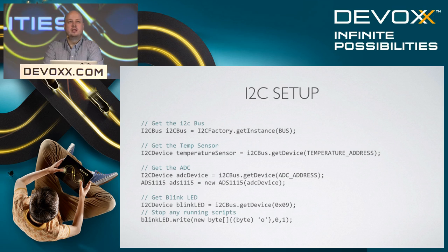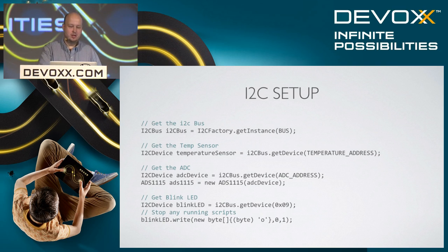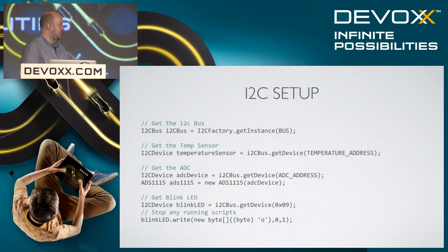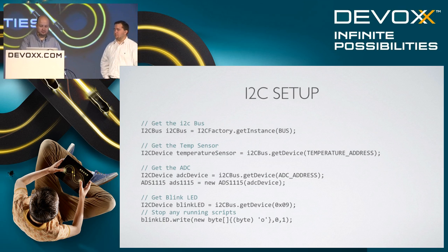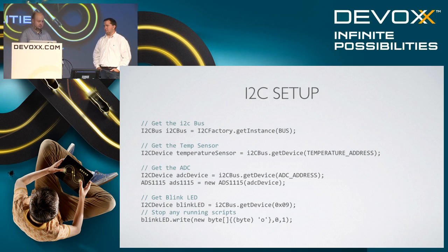So you're reading and writing unsigned bytes, but those bytes may represent a 12, 14, or 16-bit number, so there's a bit of bit shifting you have to do, and we'll show an example of that. In fact, of the entire project, this is the most cumbersome. So it got encapsulated into its own little class. Other than that, everything was really straightforward.